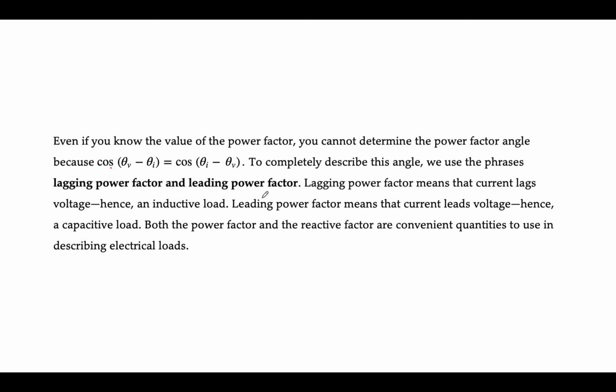Power factor is always stated with respect to whether the current leads or lags. Lagging power factor means that the current lags the voltage and you have an inductive load. Leading power factor means that the current leads the voltage and you have a capacitive load.